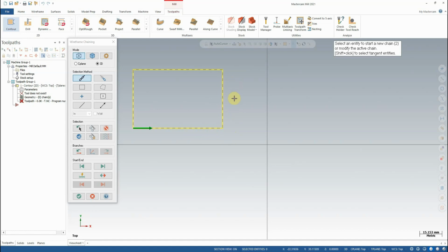Conventional milling has a few downsides, one of which being that it has a tendency to pull the tool into the work. This can result in incorrect sizes, resulting in failed tolerances and scrapped parts. While this is not always a problem, and it greatly depends on the rigidity of your machine and the type of cut you're attempting to make, generally, climb milling, the opposite of conventional milling, is usually preferable, and there's actually a number of reasons why that's the case.